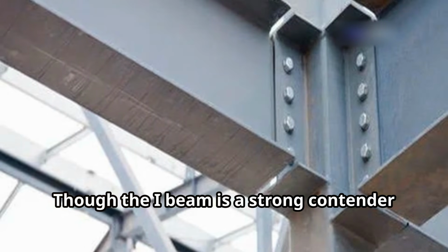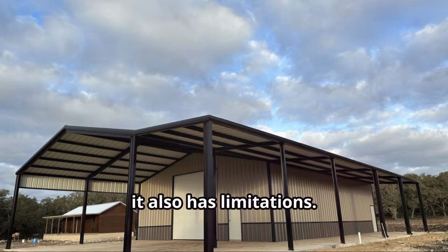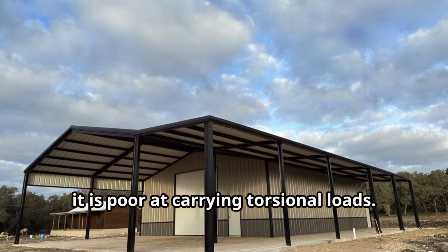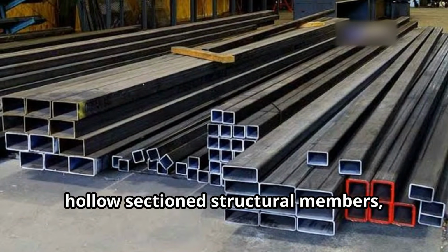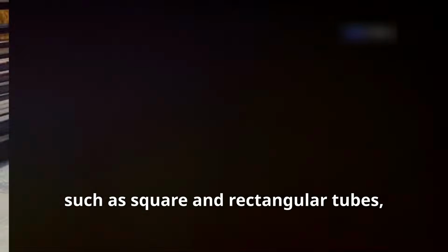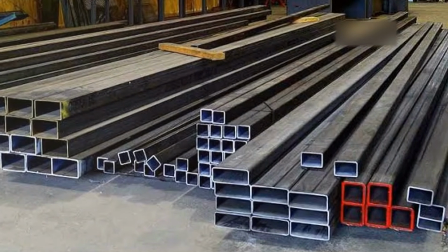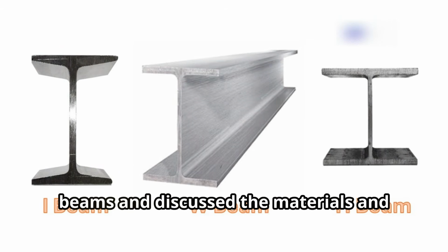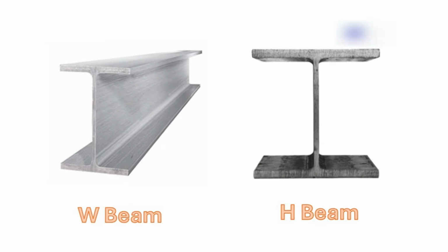Though the I-beam is a strong contender in structural applications, it also has limitations. Because of its reduced cross-section, it is poor at carrying torsional loads. For torsional loads, hollow-sectioned structural members, such as square and rectangular tubes, provide better results than I-beams. So far, we have gone through the three types of I-beams and discussed the materials and manufacturing processes.